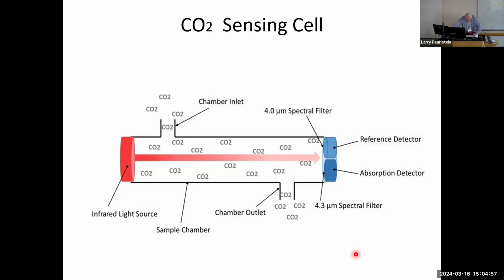There are two methods. One is very similar to the NDIR, but it uses 5.3 micron wavelength instead of 4.2 micron wavelength. They have different absorption bands for the different gases. But there's also one called chemiluminescence, chemical emission of light. If you mix NO with ozone, they react and produce light near the blue end of the visible spectrum.